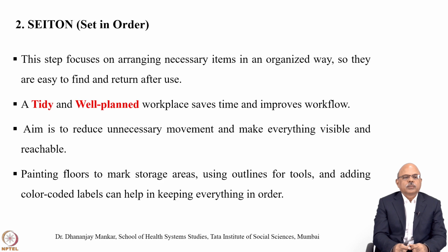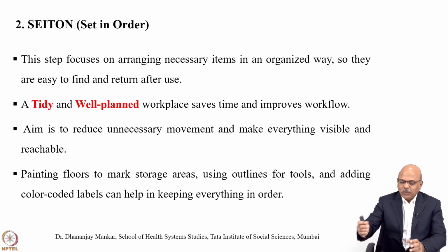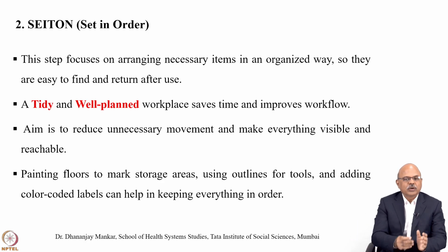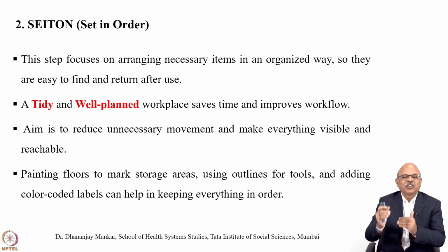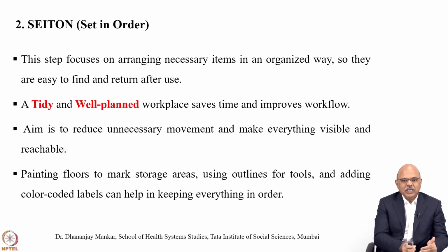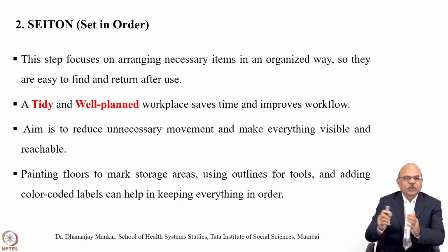Second comes Seiton, set in order. It's a Japanese word and we are simplifying it. This particular step of set in order focuses on arranging necessary items in an organized way. Whatever items you got in the first sorting, now you are arranging them in order, so they can be easily found and returned after use.